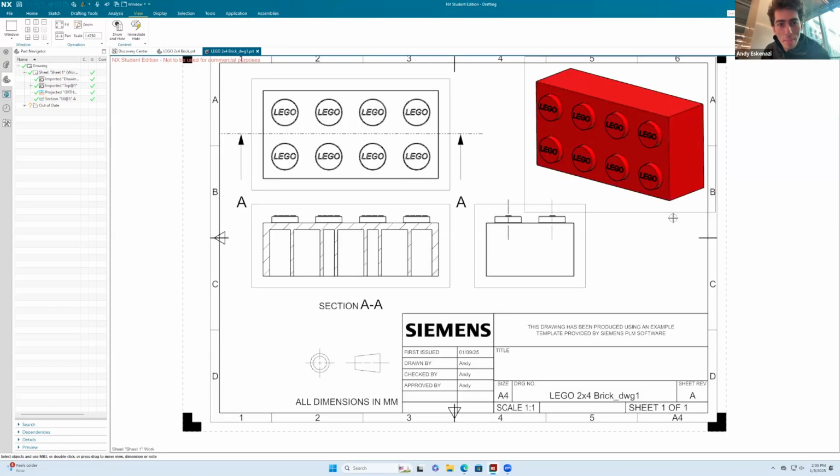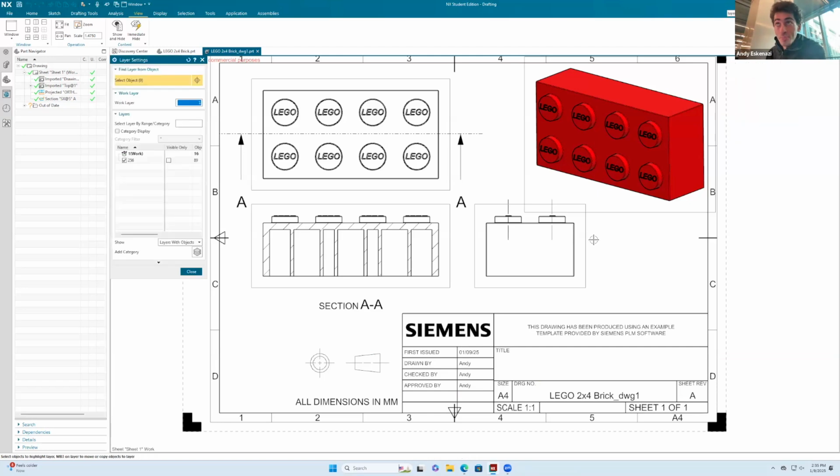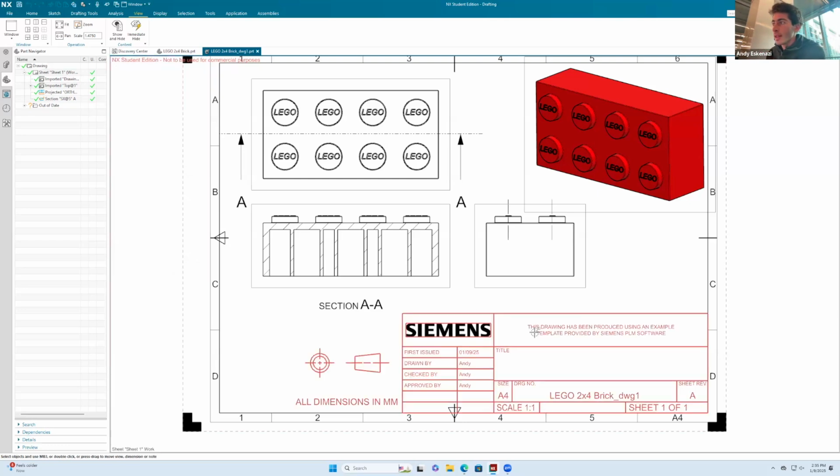Okay, now yes, I'm back. I think I figured it out. I was just trying to modify the size of the table. Reality is that upon looking it up, you have to type up here, you have to put layer settings. On your layer settings, something like this will appear. You have to make sure that that 256 is checked. Once you're done with that, then you can actually right click here and you're able to do fun stuff.